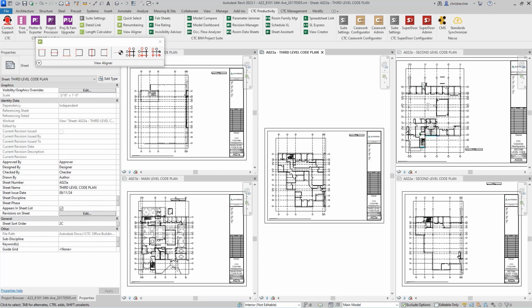There will be a level of consistency there. Again, it's not perfect for every situation, which is why hopefully either the level or the grid option helps in that respect. But yeah, scope boxes are going to be a big part of the view placement if you're using them. They will help quite a bit.